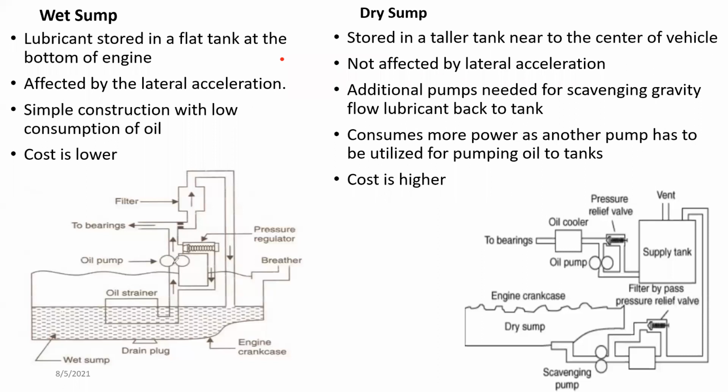Then it is pressurized, and if the system's pressure is too high, the pressure relief valve will open and the oil will return. Assuming the oil is properly filtered and pressurized, it is then sent to all the components, filters and everything. Don't worry about this section, I'll explain it later. This is how the usual wet sump lubrication system works.